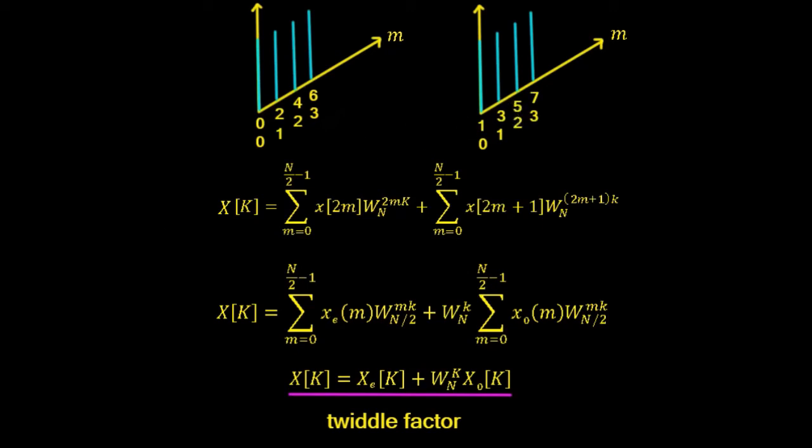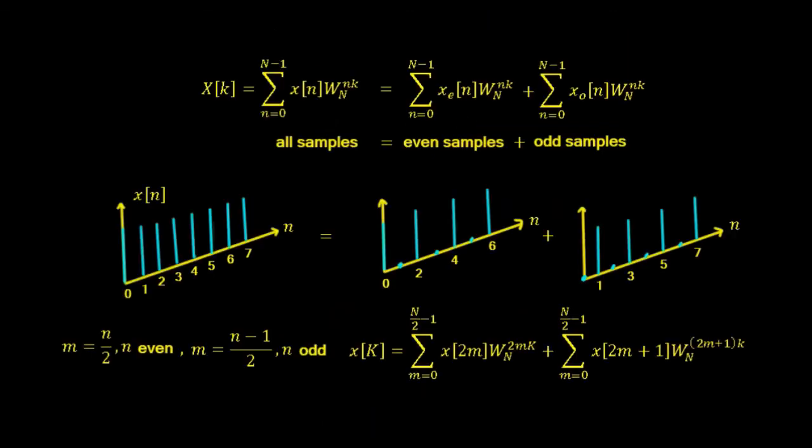So you can see that in a previous page. So you can see this here, the 1, 3, 5 and 7, the 1 is actually sitting here, so in effect the twiddle factor shifts everything to the left. So that's a multiplication with a complex exponential, which is equivalent to shifting the function in the time domain.